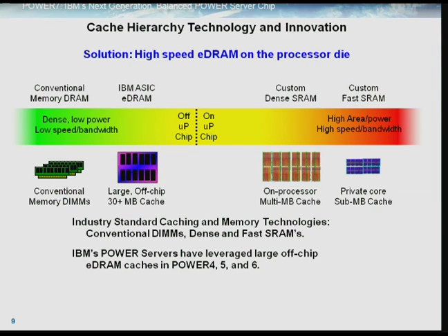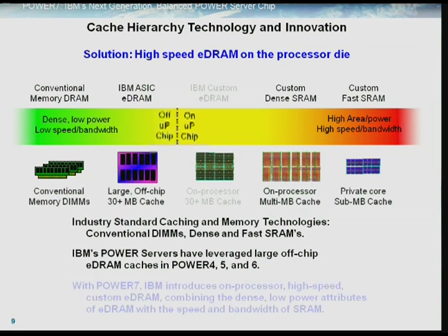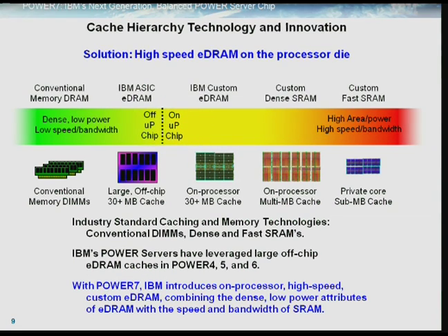We, as I said, had another bullet in our gun over the past several generations, which was this embedded DRAM capability, a DRAM that's a lot faster than conventional memory technology, still bringing a lot of the density and power value of DRAM. And now with Power 7, we have invented the way to mix all the secret sauces together on the same chip, put the deep trench, put the different process steps in there, and not take down that super duper high frequency logic device performance.